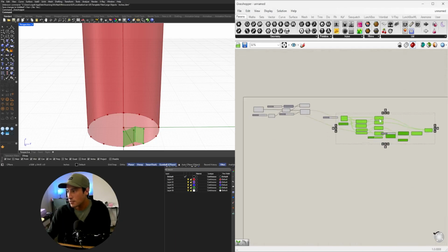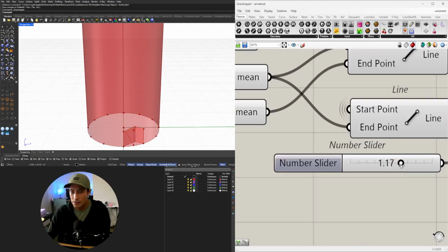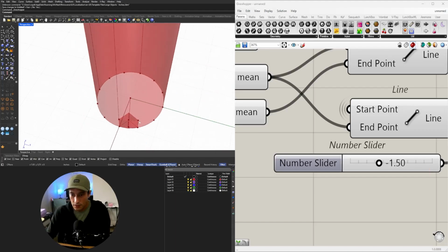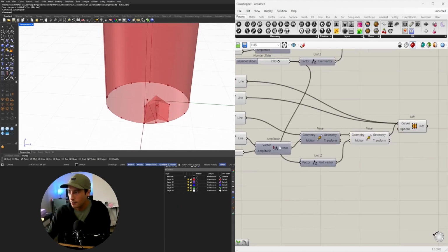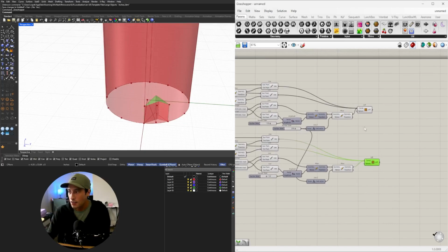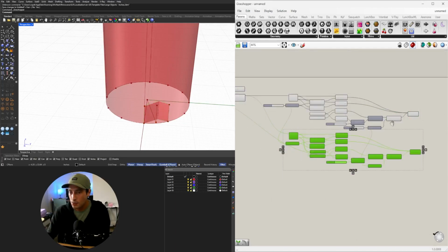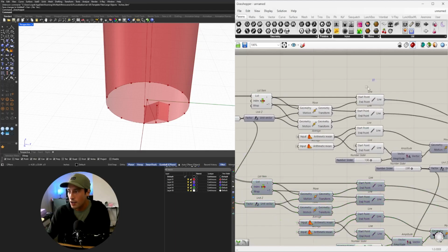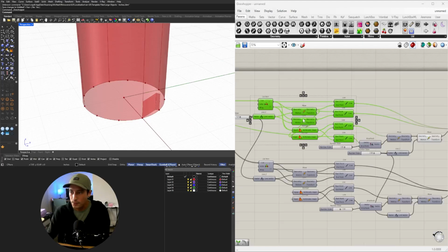So I'll take this, slide it down, tap Alt, and now we can have one that offsets out and one that offsets in by -1.5. The reason why, and you'll see this, is let's keep this as the original, so we'll hide this one. We will also hide the line segments that create all of that, except for the module.